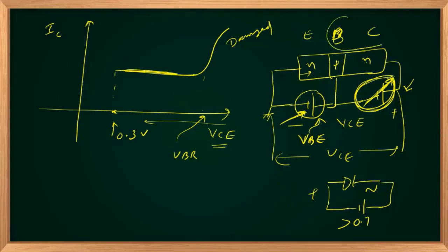When this junction becomes less reverse biased or forward biased, that will block the minority carriers crossing the second junction, that is, electrons emitted from the emitter region, right? So the number of electrons collected by the collector supply will decrease because we are reducing the reverse bias by decreasing this voltage. And this is anyway positive, greater than 0.7 volts. If this is negative, VCE will become less than 0.7. Suppose this is at 0.7. This is negative, which implies VCE will become less than 0.7.